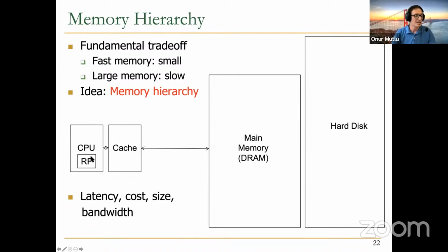And you can think of register files as part of that memory hierarchy also, and they are actually, except they're managed by the compiler or the programmer. You put data from the cache into the registers. When we introduced the register file in lecture 10, we discussed that the register file works because you have locality of reference in values that you manipulate. You basically store the values that you're going to need very quickly into the register file. And you have a small register file, 32 elements or 16 elements. GPUs have larger, of course, but 32 elements is reasonable today. And the compiler or the programmer manages this one. Caches are usually automatically managed, and we're going to talk about that.